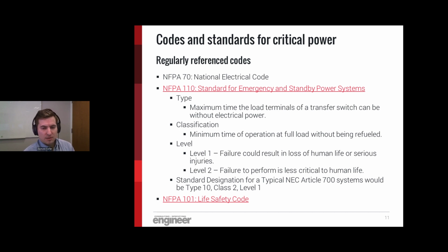The type defines the maximum time that the load terminals of a transfer switch can be without acceptable power. Classification is the minimum operation time at full load without having to be refueled. And then the level determines the installation, performance, and maintenance requirements of a system. Typically, there's a Level 1 system or a Level 2 system. Level 1 could result in the loss of a human life or serious injuries, and Level 2 is less critical.